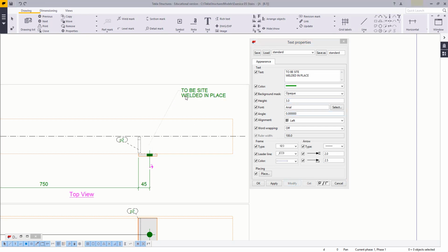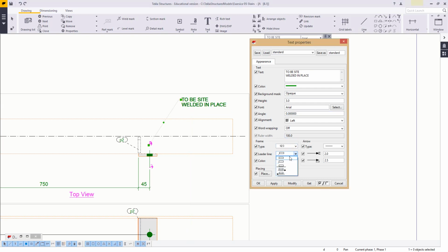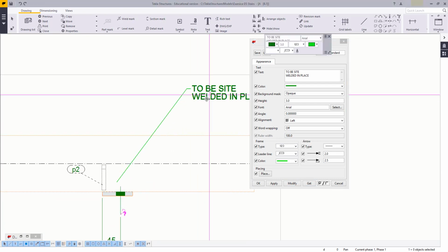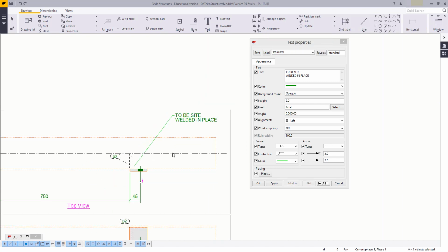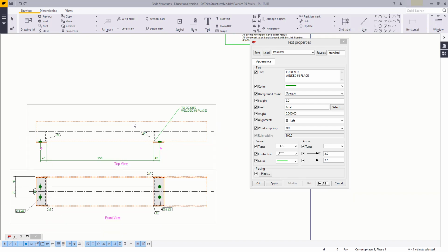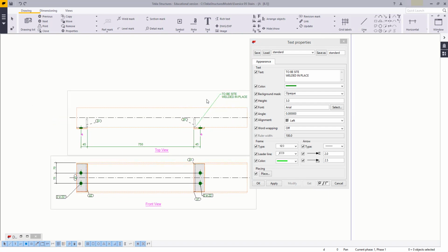and of course you can add whatever other notes you need to this, something like specific corrosion protection, their procedure, what they need to do, according to what specification they need to do it, if the welder needs to have a certain certified status, or pictures need to be taken and sent to the engineer, all that type of stuff you can add to this note.